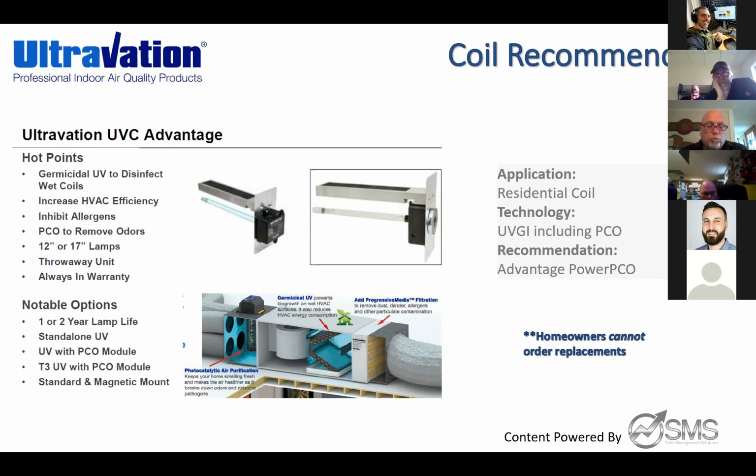This is a throwaway unit, so what that means is, instead of the contractor going back each year to replace just the bulb, he'll actually replace the entire unit, which makes it a lot easier, and it's about the same price as just a bulb. So all you have to do is take those 2 to 4 screws, pull out the unit, pop in the new unit there. If the contractor is keeping up on his maintenance every year, this will always be in warranty as well.